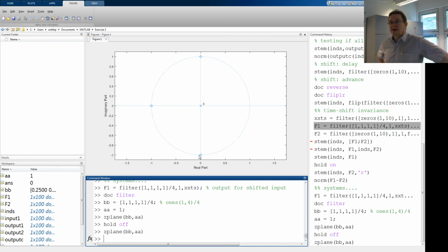Okay, one warning: if I get any of those zeros and poles mixed, it means that you have messed up or mixed the A and B parameters. So one hint: I have this system, it is stable, meaning that the poles are inside of the unit circle, as they are, for example, here at the center of the unit circle. Okay, so that one already gives us information. Yes, this is also a stable system. So the 4-point running average system is stable. Excellent.